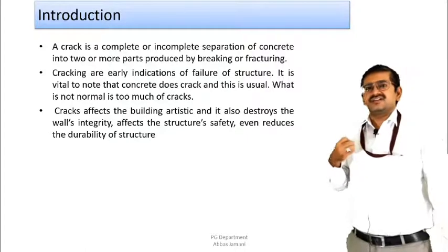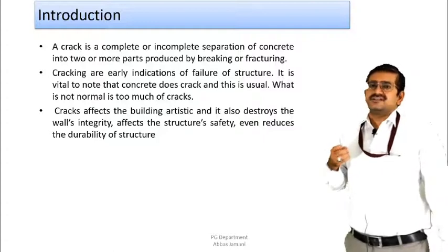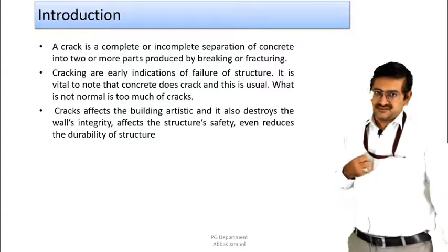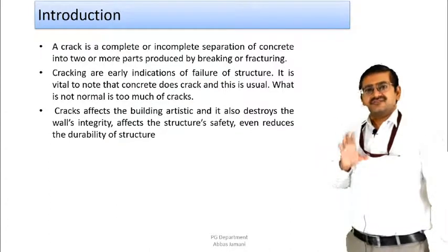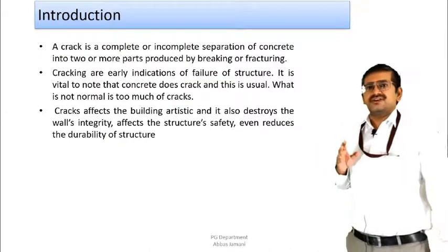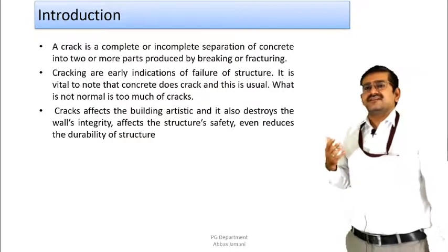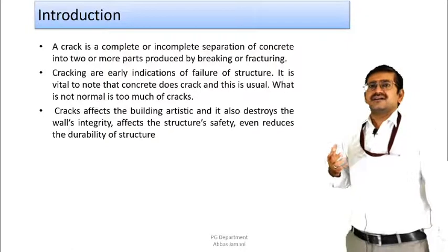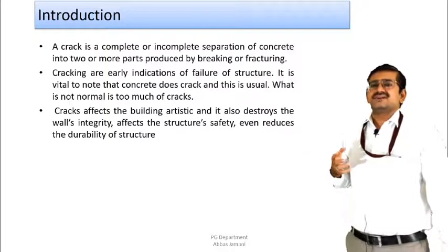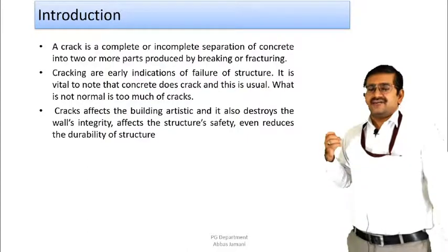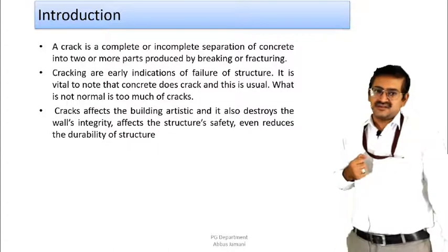But if it is a non-structural crack, then it will only be an issue of aesthetics, and it will not compromise the safety or the service life of the structure, right? So it is saying that the visualization of cracks is normal, but what is not normal is seeing too much cracking, that is, the magnitude of the cracks, the depth of the crack, the width of the crack, or the spacing of the cracks being very close to each other. In that case, there is a possibility that it is going to have an effect on the service life of the structure, or you can say the stability of the structure overall, right?